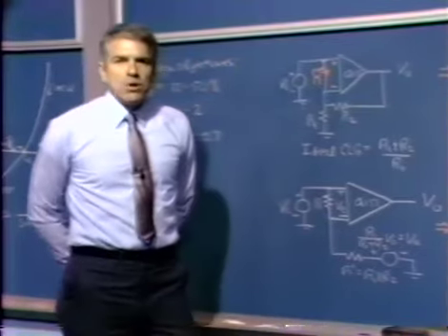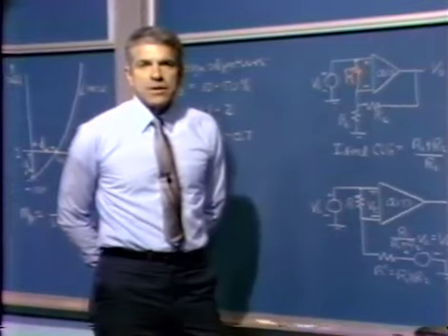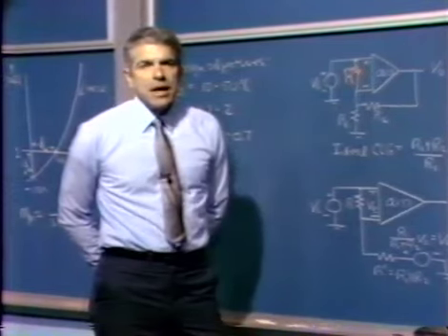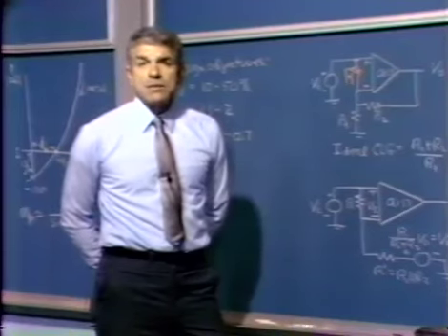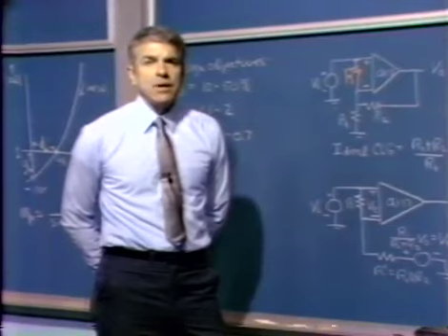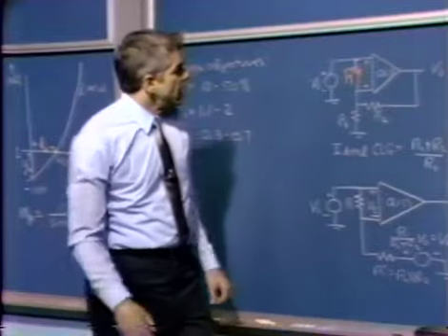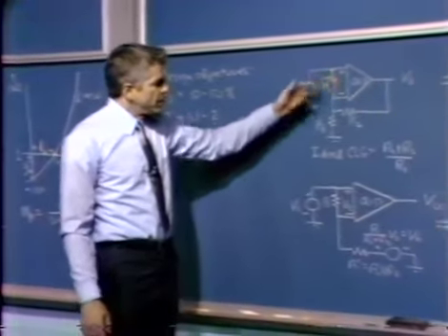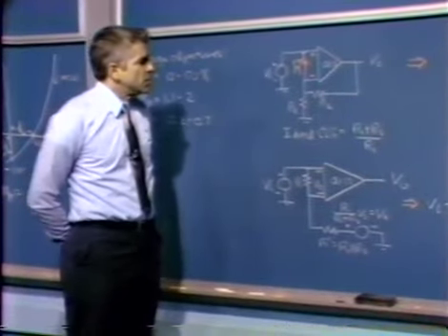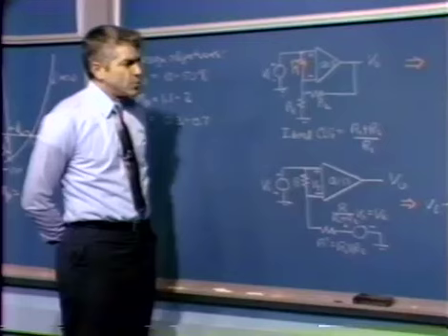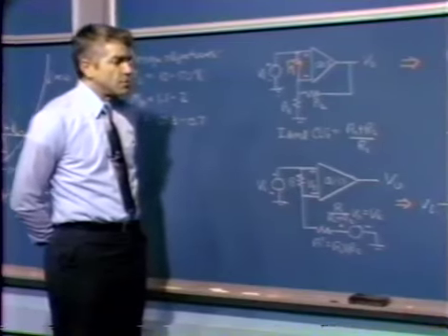Well, suppose we'd like to take such an amplifier and run it at a closed-loop non-inverting gain of 2, for example, but the manufacturer only guarantees stability if f is less than 1/5. In other words, if we attenuate the signals fed back by a factor of more than 5. We can use this sort of approach in order to attenuate the signal fed back to the amplifier, lower the loop transmission magnitude so that the amplifier configuration becomes stable.